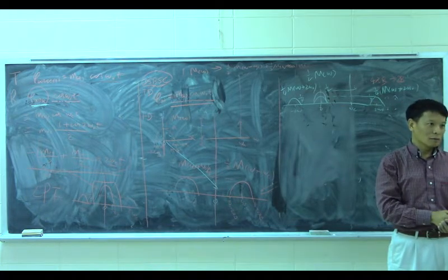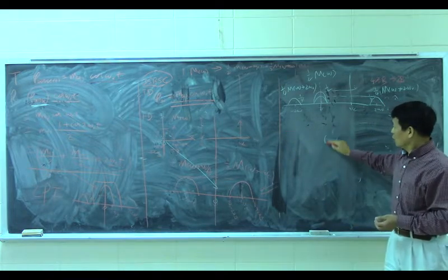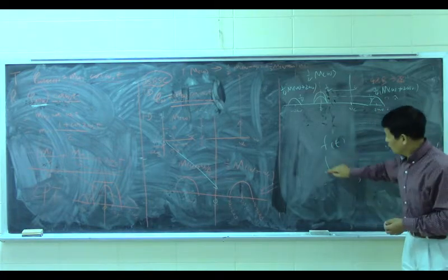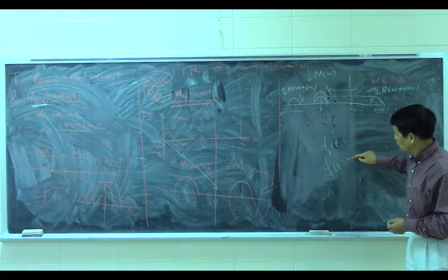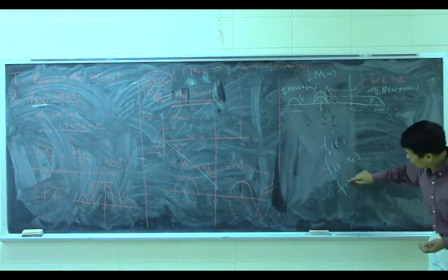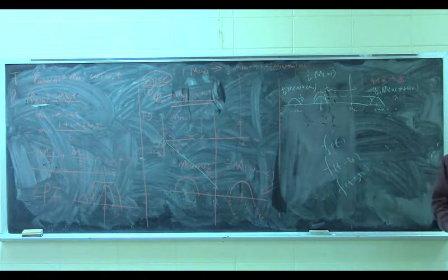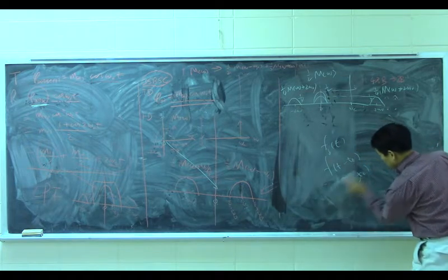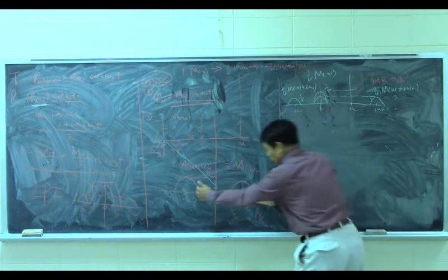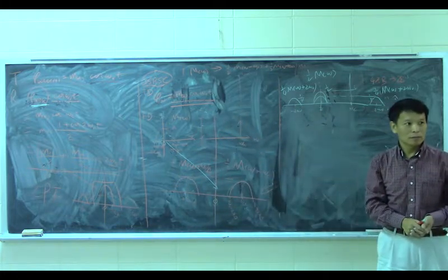How come that one is minus and that one is plus? For the shift, to make it go back to zero? If you have a signal f(t), from here to here, t minus t0 means you shift this waveform to the right by t0. If you get t plus t0, that means you shift this waveform to the left by t0, right? So both of them shifted right, or both shifted left? This both shifted to the right, and this both to the left.